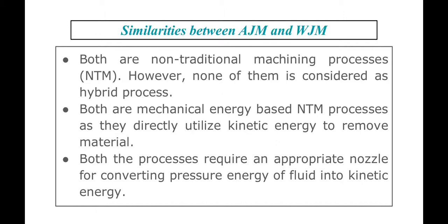So again, the next one is that both the processes require an appropriate nozzle for converting pressure energy of this fluid, air in case of abrasive jet machining, and water in case of water jet machining. So this pressure energy of the fluid is going to convert into kinetic energy in the form of a high velocity jet. Okay, so this is a similar point.